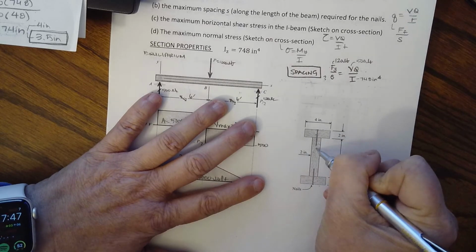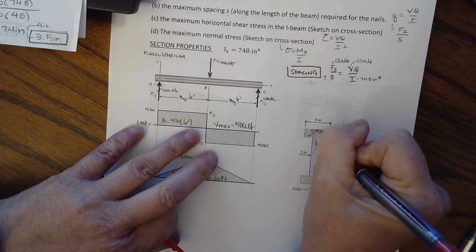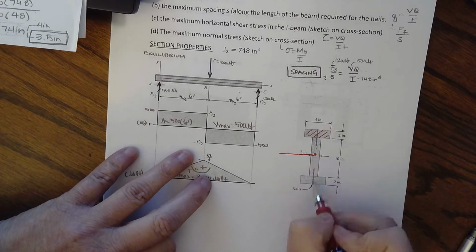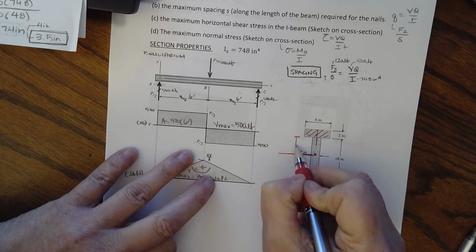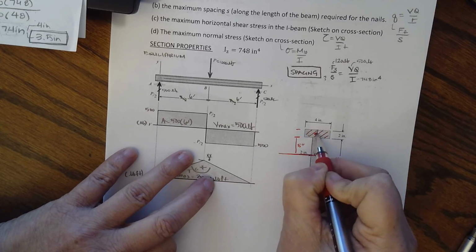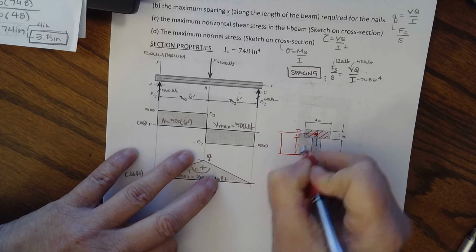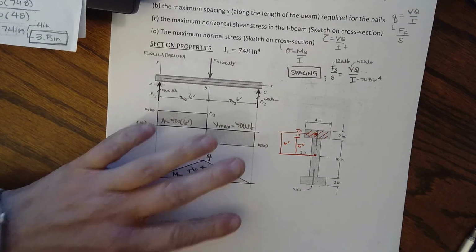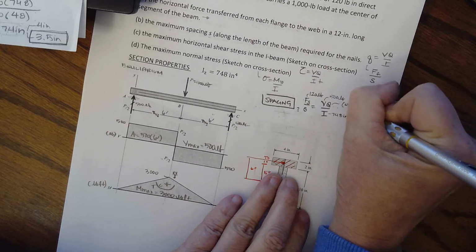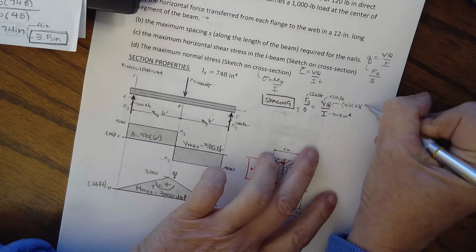What am I nailing onto the system? I am nailing this piece of wood onto the system. Because of symmetry, I know the centroid is right in the middle. It is 5 inches up, and then here we are 2 inches up. So if I want to find that centroid, 1 inch, 1 inch, it is 6 inches up to the centroid. So when I'm looking at Q, I'm going to have the area that I'm nailing on. So I have 4 times 2. I have to walk 5 inches up plus another inch to the centroid.